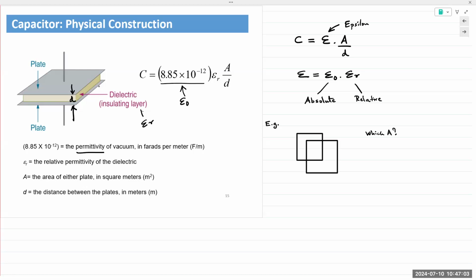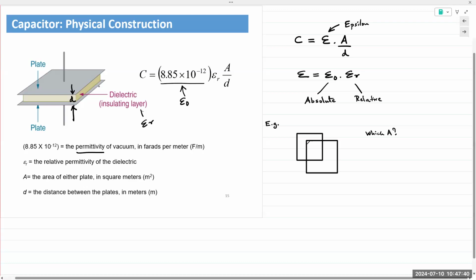So when I said conceptual, here's the concept I want everyone to think about. The two palms of my hand together, I have a capacitor, right? If I take one away, is there a capacitance? No. So I need to have a second plate to have a capacitance. So now look at the figure again. Which area has two plates present and which has only one? Absolutely. The answer is plates that are overlapping.